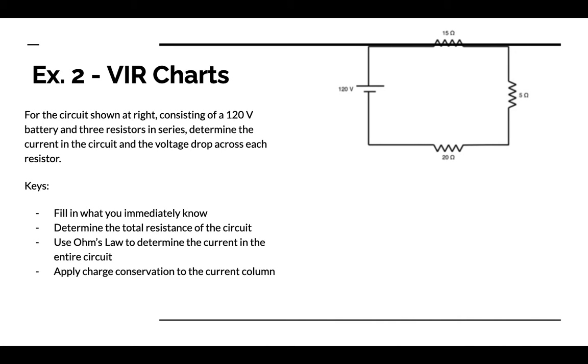Because the main idea here is we'll always typically know what the voltage source is, aka we can read a D-cell battery has 9 volts or 6 volts or whatever it is. And most of the time we know what the resistances in the resistors are because we can design the resistors for the resistance that we want. The thing that we're interested in calculating that we can't always directly measure, at least without the help of a voltmeter, is the current and voltage drop across each component of our circuit. And so that we do need to be able to calculate.